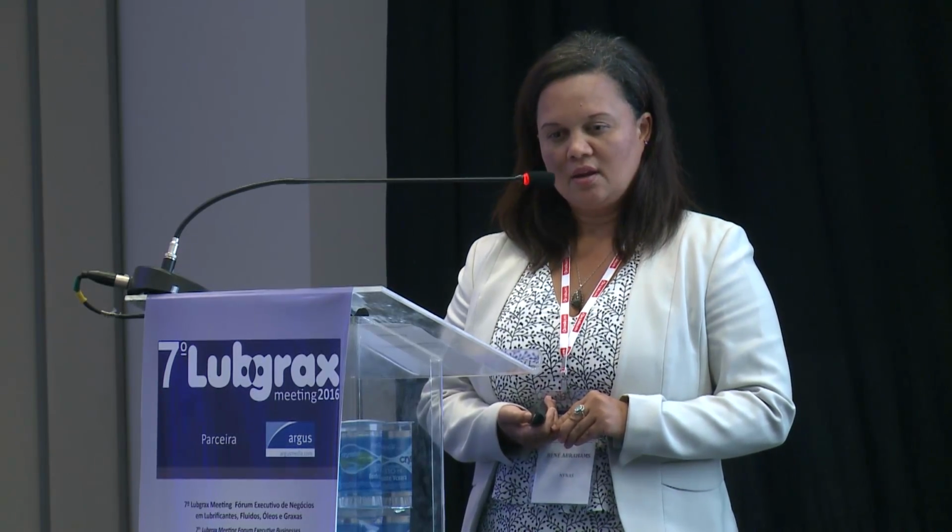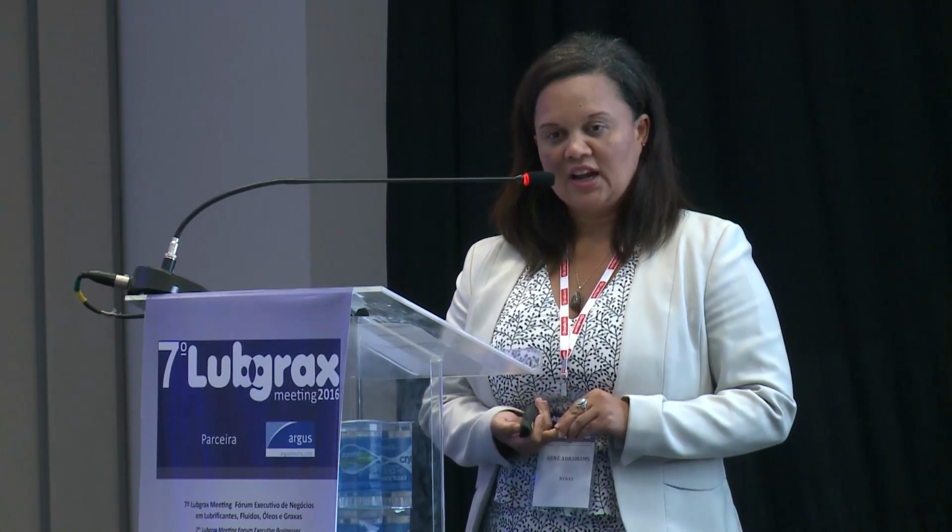Right, and then this is now the higher temperature sweep. Again, pretty similar. We see that grease B, which is the NYBase 500, performing slightly worse, I would say, than the other two greases. I think this is because that particular oil had a lower viscosity index, so I think we're seeing more of the temperature impacts. The other two had VIs of over 96, whereas that black graph was about 79.